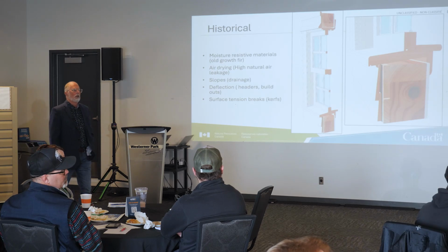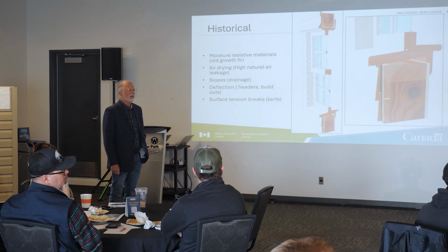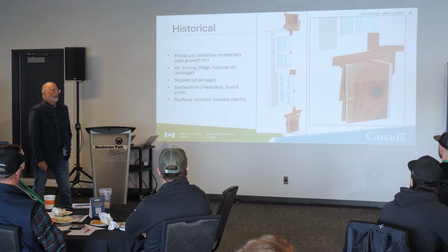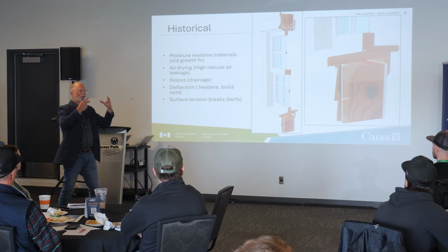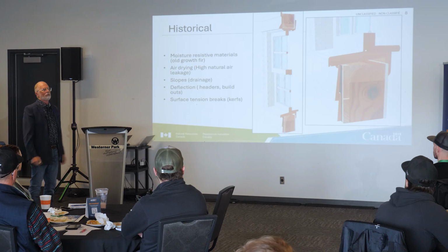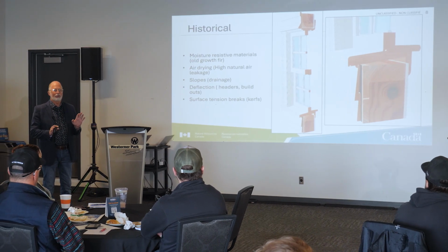Yeah, thanks, Darrell. It's always been my understanding a huge part of that was mechanical systems too. Mechanical systems drew combustion air out of the building. Everything had a chimney, like your neutral pressure plane at the ceiling. That's another one, right? In the old days, you had a furnace with a B vent. So as the air got sucked through, the air outside was drier, it came in, it warmed up, it absorbed all the moisture. So you have all these things going against you now with a modern constructed house.